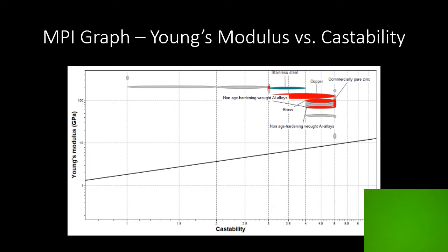The cheapest method for the manufacture of many copies of a small part is casting. As such, we compared the castability of each of the 6 considered materials. This parameter was given a weight of 0.2. The best materials in this category are zinc, aluminum, and brass.